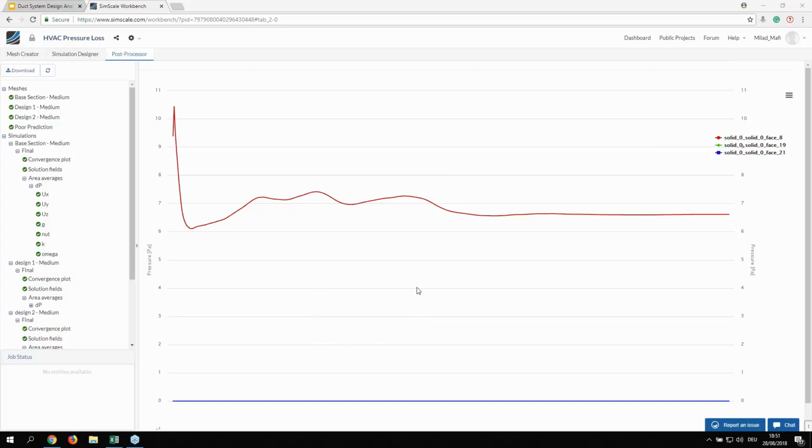Walid, for sure this is possible, and the only thing limiting you, at the end of the day, is having the right CAD model. In this case, you would simulate the dampers as static parts, and then measure the momentum, for example, or the force acting on them, and these values can then be translated and used to determine the opening angles of the blades.